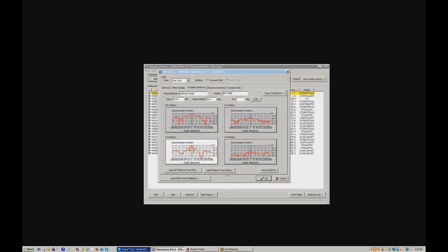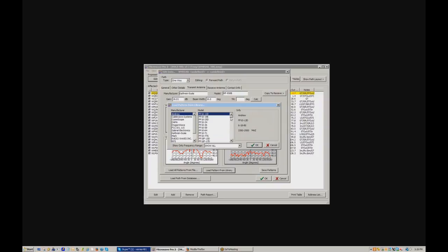So what I'm going to do is go into the library and very quickly show you that we have to choose a 950 megahertz antenna. And how do you tell which is 950 megahertz? Well, generally these are listed with the megahertz indication coming up second. So if you choose this 13, let me see, I'll use one here. This is 25 megahertz, FP10. 10 is approximately the gain usually of this antenna. And so we can see here that we're going to be in that mid-range, but that's not what we want.